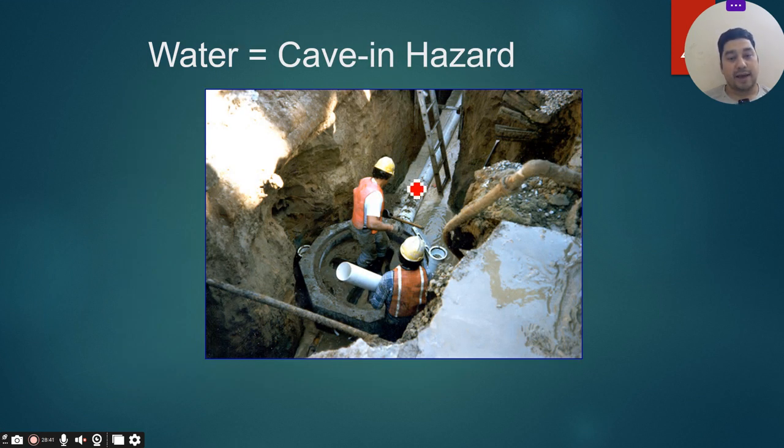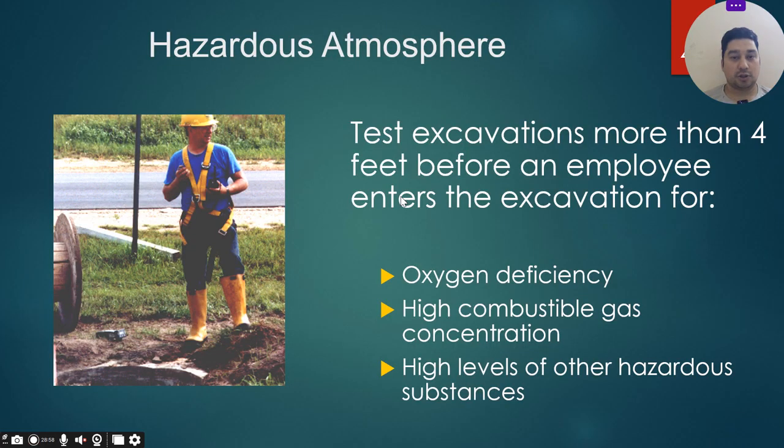Water equals cave-in hazards, very common. You can see here the workers are working. There is water also, so that should be removed first. There is too much water here, and it is not protected also. A protective system is not installed.